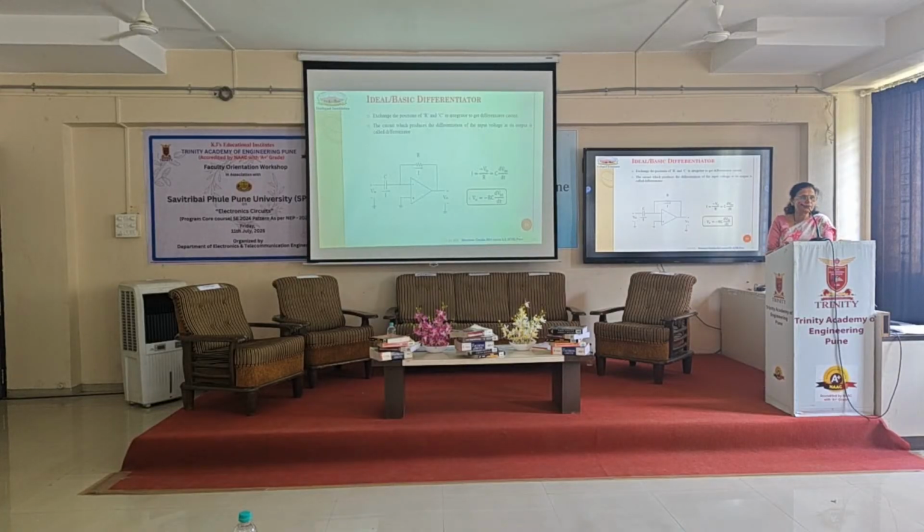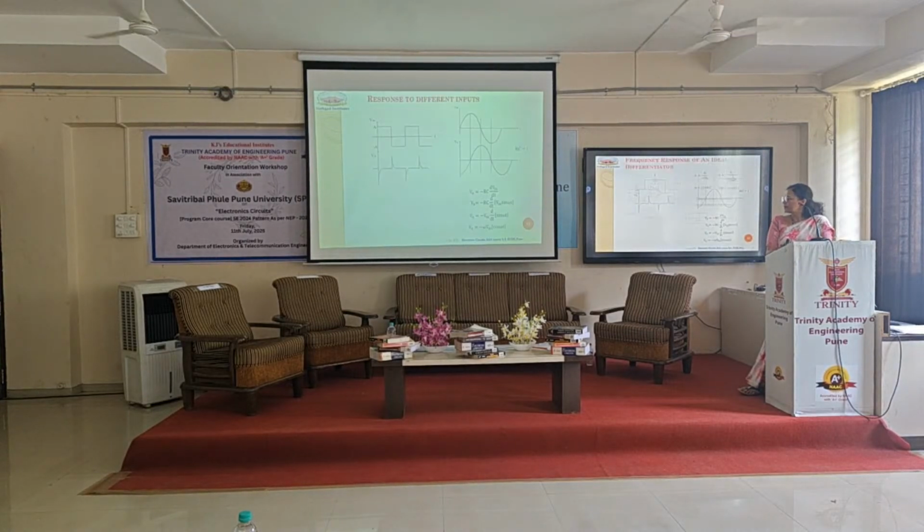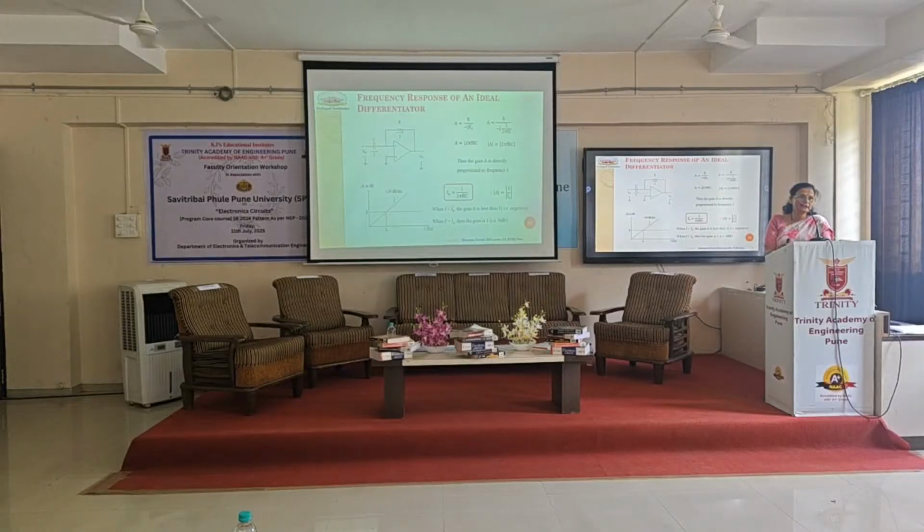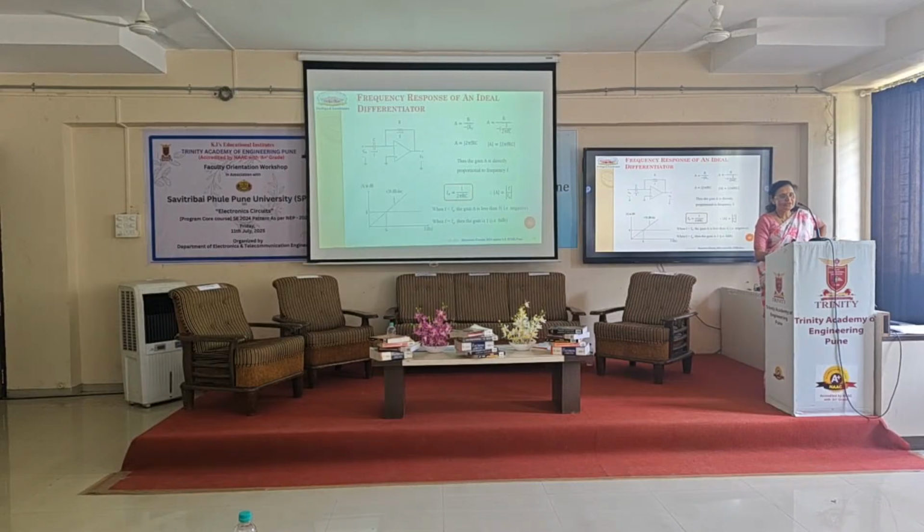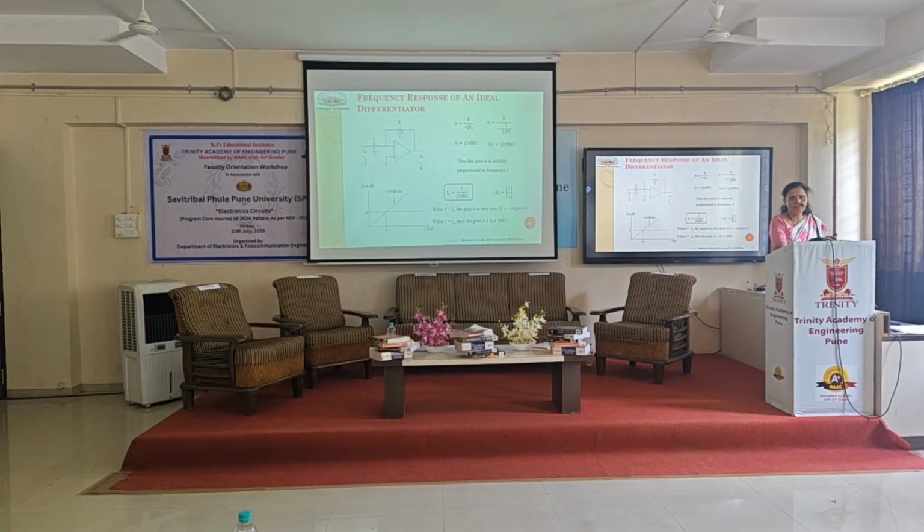It is exactly opposite to the integrator, that's why components are changed. And by going through the derivation of the gain equation, again the frequency response is very important, because in both the circuits we are looking for the frequency response. No doubt, indirectly they are working as filters, and they work as an integrator and differentiator for a particular range of frequency that we are supposed to find out.